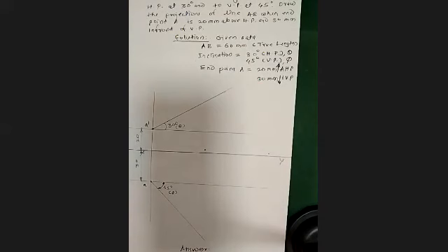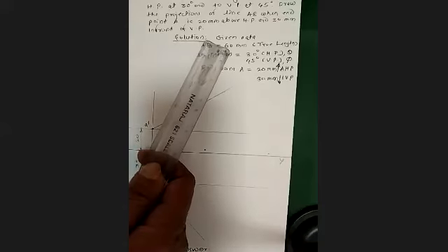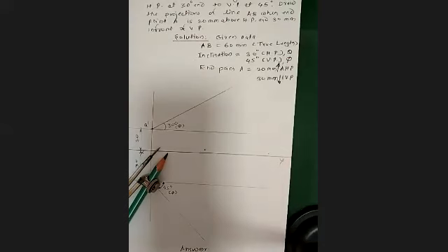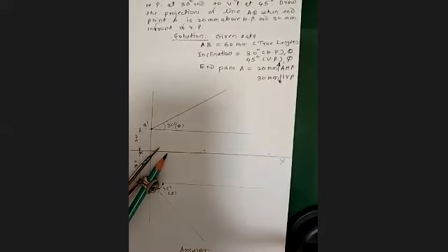Now you know about the length of the line. True length is given to you. This true length of 60 millimeter is known to you. So we'll take the length now, that is given, 60 millimeter. Either you can take this distance 60 with a divider, or you can measure directly by using the scale. Whatever is convenient to you, take 60 millimeter.